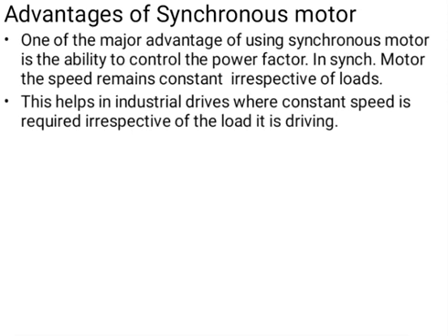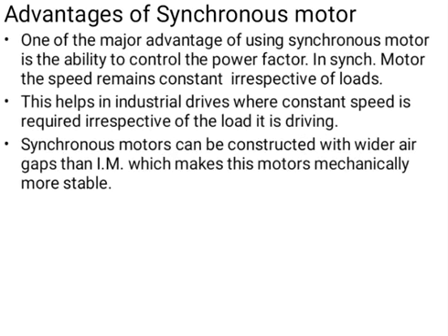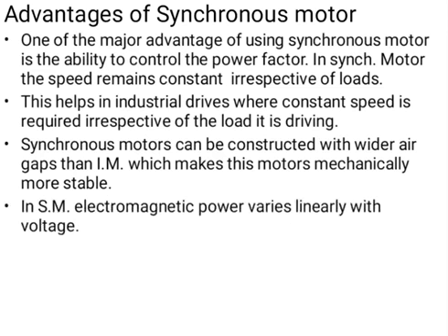Second, this helps in industrial drives where constant speed is required irrespective of the load being driven. Third, the synchronous motor can be constructed with wider air gaps than an induction motor, which makes these motors mechanically more suitable.